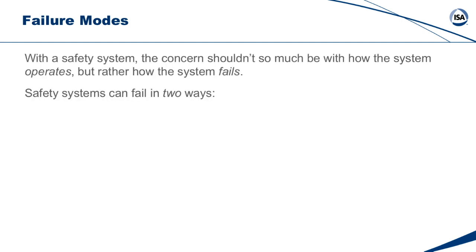So when we're talking about PFD, probability of failure on demand, we're really talking about one particular failure mode of systems. And safety systems can actually have two failure modes. There have been people who had relay safety systems replace the relays with PLCs, implemented the same logic, thought they made an improvement with the newer technology, and they had accidents because they did not understand this extremely important concept.